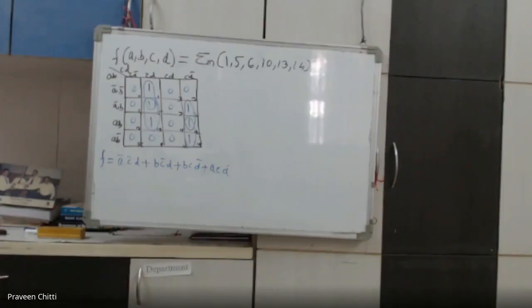Sorry for the interruption. So now how do you go about this further? There are two ways. They ask you to solve the above example and implement it. What you can do is draw one more K-map, and then group zeros and write the expression directly in terms of POS.